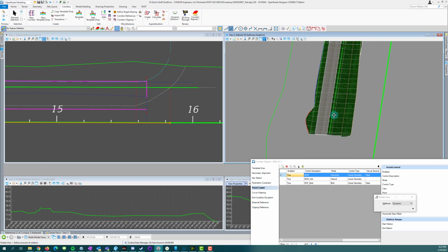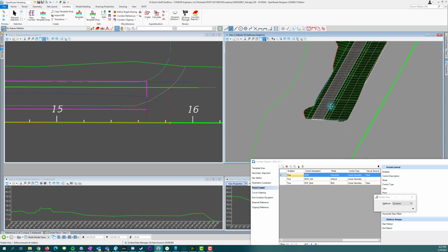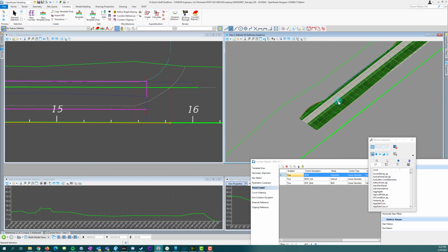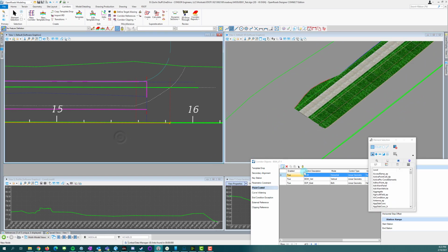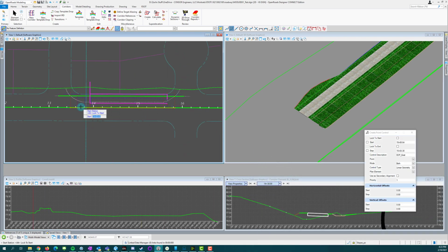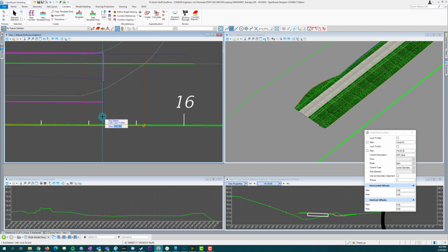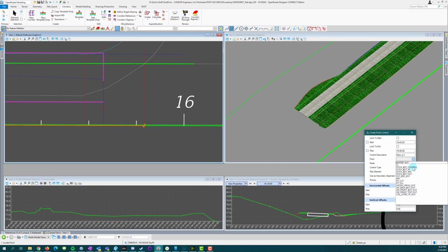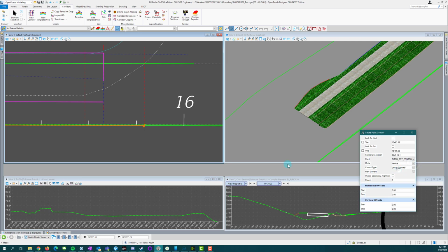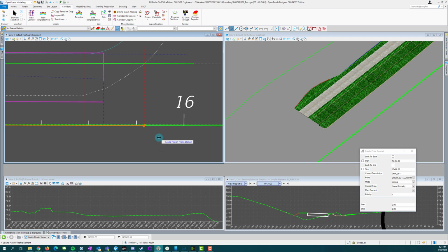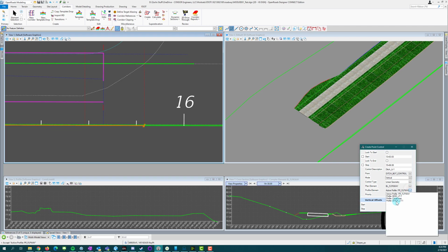Okay. So the problem is now that ditch is still getting confused because in the template it's drawn a little bit too high. So we have to add the ditch profile, and we can really only add it between here where we have the ditch and here. So this is going to be ditch left one and ditch bottom control, and it's just a vertical control. So that, remember, that ditch profile is along our center line again, and we want to go ahead and find that ditch left one.